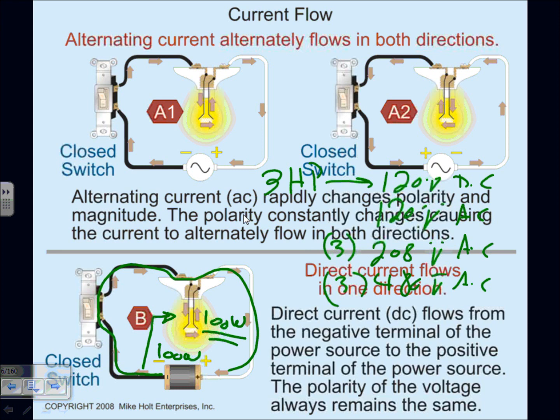Which one will consume more power if you run these voltages and the same horsepower? Granted, we have to design it to be run at these voltages. You can't just have one motor, guys, that runs at all these voltages. You have to design it at 3 horsepower. Which one do you think is going to consume more power? Same. Did you guys get that one? The same amount of power, 3 horsepower. So I can suck 3 horsepower out of the system at 120 DC or AC, or 3-phase 208, or 3-phase 480. This is the single most important thing.